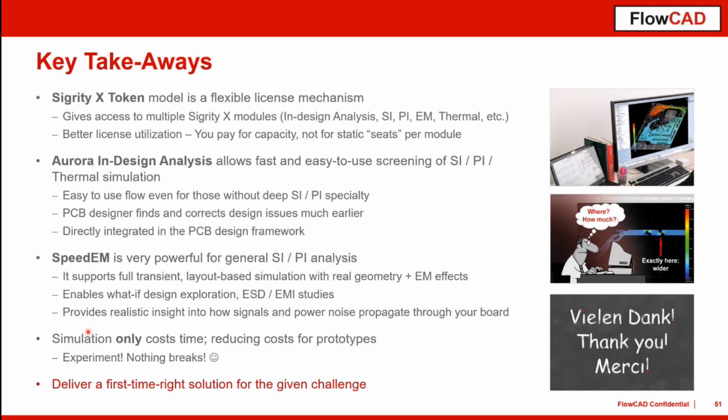But if you work in your typical PCB design editors like OrCAD X Professional or Allegro X, none of those licenses will be used as long as you do not start the analysis. That means, depending on the licenses you have for your PCB design editors, you do not check out any of these tokens.